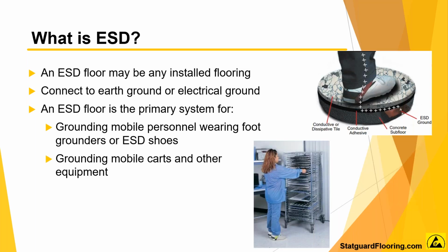ESD flooring can be any type of permanent material such as ESD tile, ESD matting, or ESD epoxy and paints, to protective materials such as dissipative floor finishes. Not only does it minimize charge generation, but it allows for mobile grounding of personnel, carts, and ESD chairs. Shelving and mobile carts on ESD floor can be an ESD work surface, but they must be properly grounded, as shown in the bottom picture.